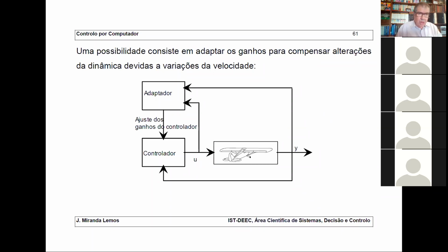One limitation is that your algorithms may not be too complicated because you have to comply with the sampling interval. And the sampling interval can be very small. If your computations are too heavy, then you don't have enough time to complete the computations within the sampling interval.